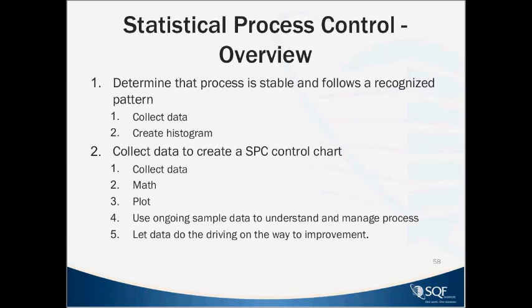We talked earlier about attribute charts, and attributes can be things like rejects. They can also be control charts if they're important quality parameters. But in either case, you've got to collect data. You've got to collect some, do the math on it in terms of calculating your control limits, put those control limits on our graph, start plotting them.